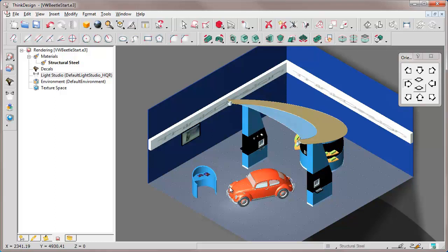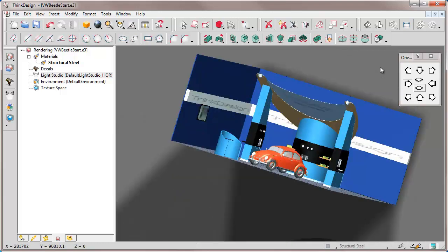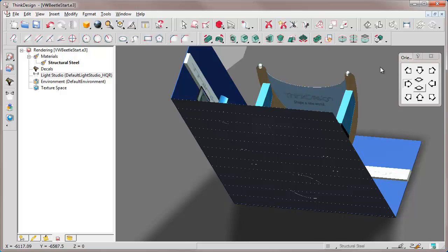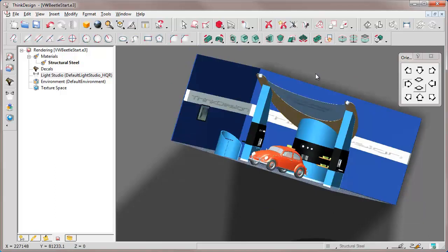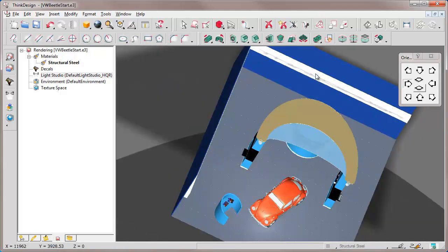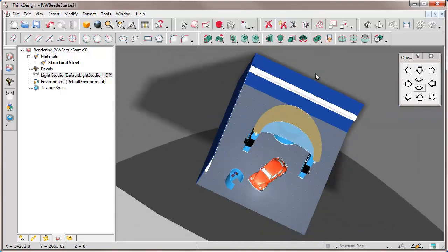Let us then rotate our model. In addition, we shall have to enlighten the lights of the two spotlights, even if the projection of the light onto the car is present. These lights, seen from the bottom, would look dark, so if we put the punctiform light inside it, we shall have the same lighting effect of the lens surface. For shortness' sake, all of these operations have already been accomplished in another model. Therefore, let us show the effect on a final model that we shall use for some rendering tests.